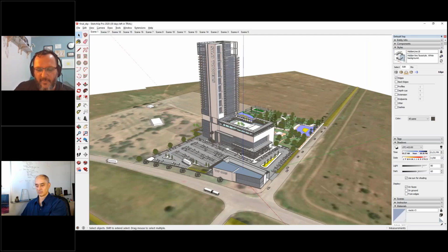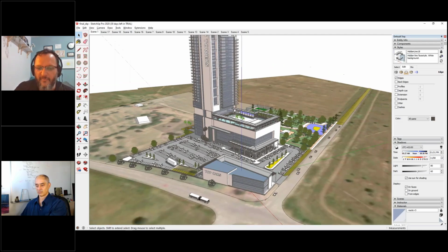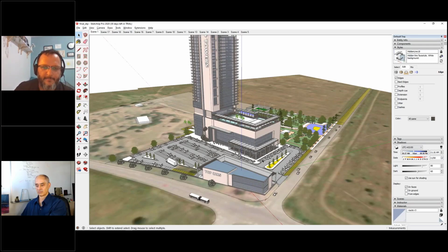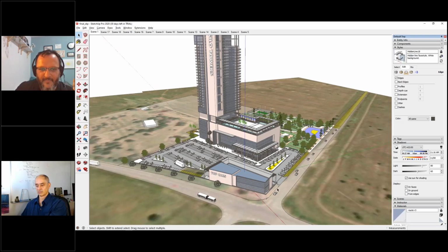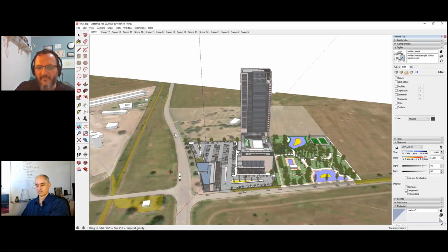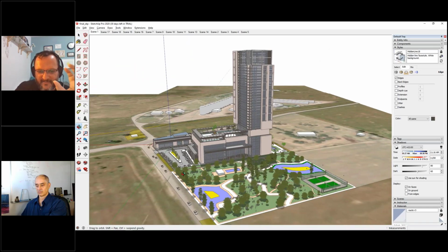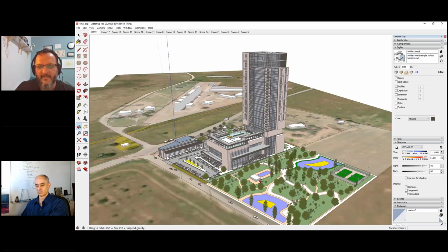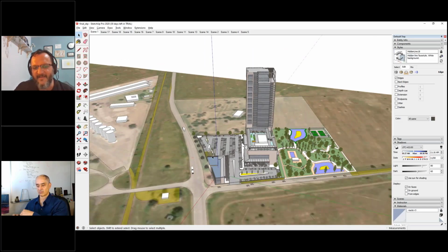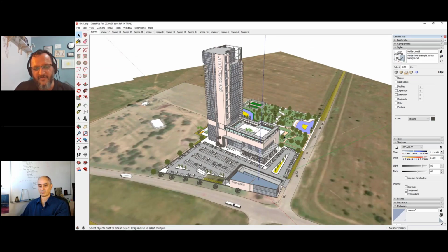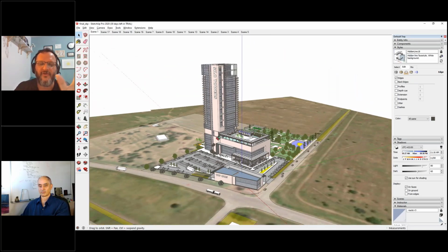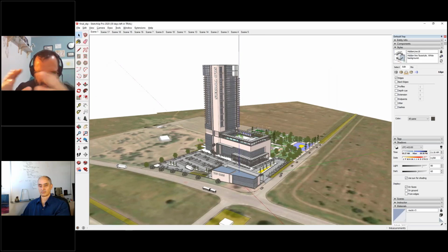And if you're really clever about your shadow system, you can produce 4 or 5 different shadows at different times of day, and you can layer them in Photoshop, and with a bit of post-production in Photoshop, you can ultimately create a stylized volumetric shadow. It's not a V-Ray shadow, it's more synthetic, but it gives the model volume. Okay, so that's it for SketchUp. SketchUp's an amazing tool. And just one last thing, I don't use SketchUp as just a presentation tool.